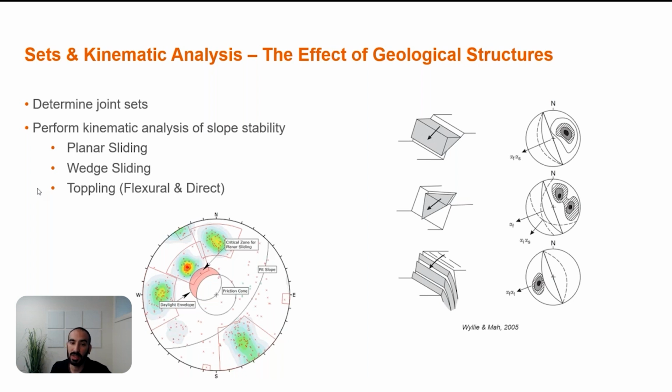So the stability of rock slopes is often significantly influenced by the structural geology of the rock. The structural geology refers to naturally occurring breaks in the rock, such as bedding planes, joints, and faults, which are generally termed as discontinuities. The significance of discontinuities is that they are the planes of weaknesses in much stronger intact rock. So the failure tends to occur preferentially along these surfaces. Therefore, the discontinuities may directly influence the stability.